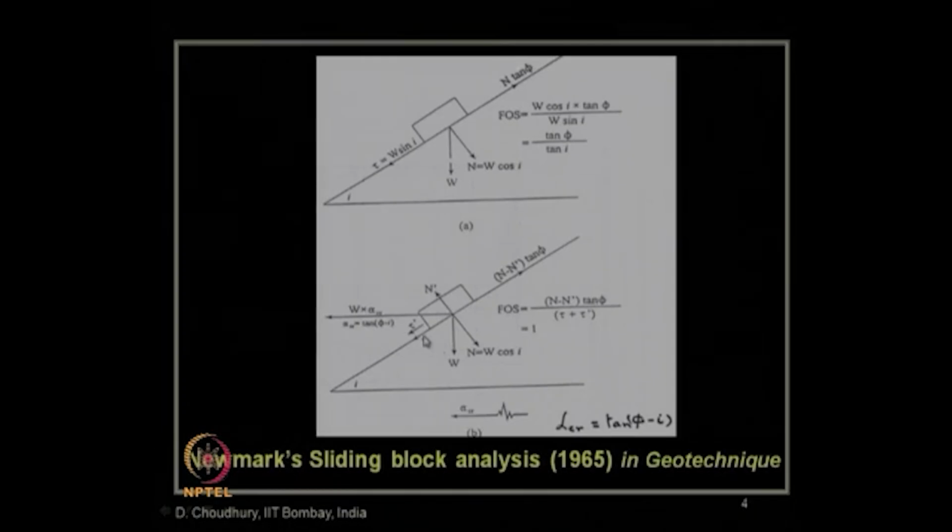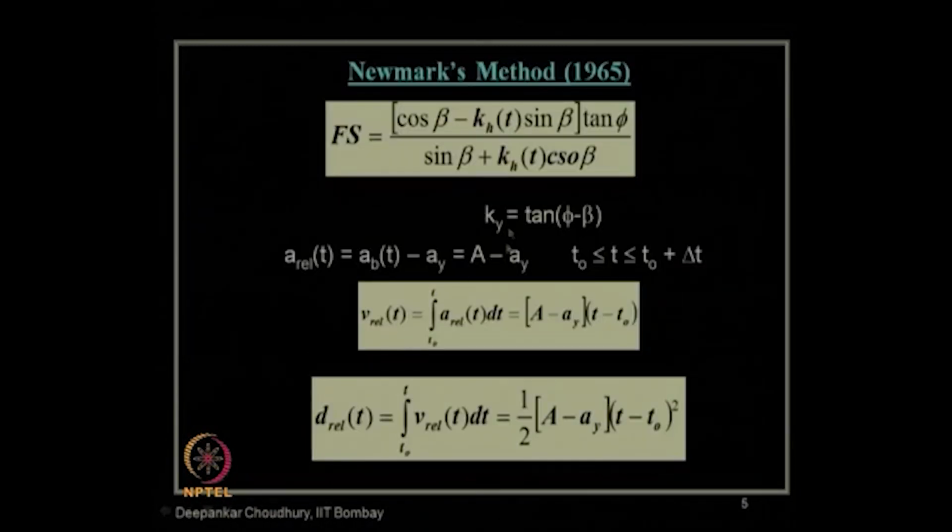In terms of factor of safety, once we equate it to 1, then the seismic pseudostatic acceleration we get is referred to as the yield acceleration. So, we have seen this equation to obtain the factor of safety against any movement of a soil block, and how to estimate the yield acceleration coefficient in this fashion.